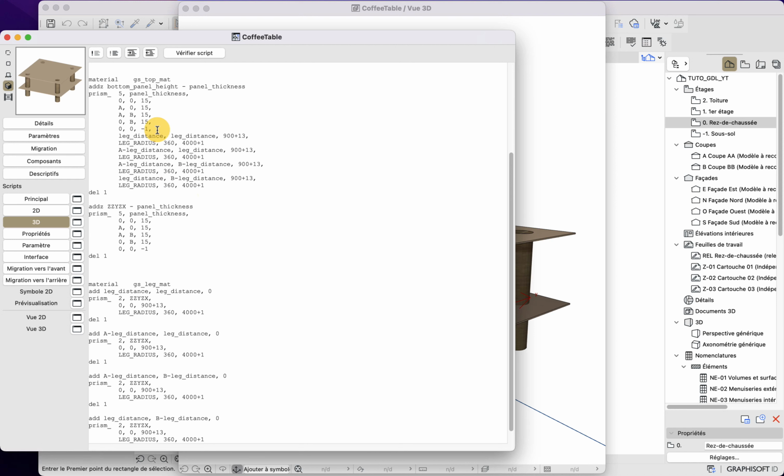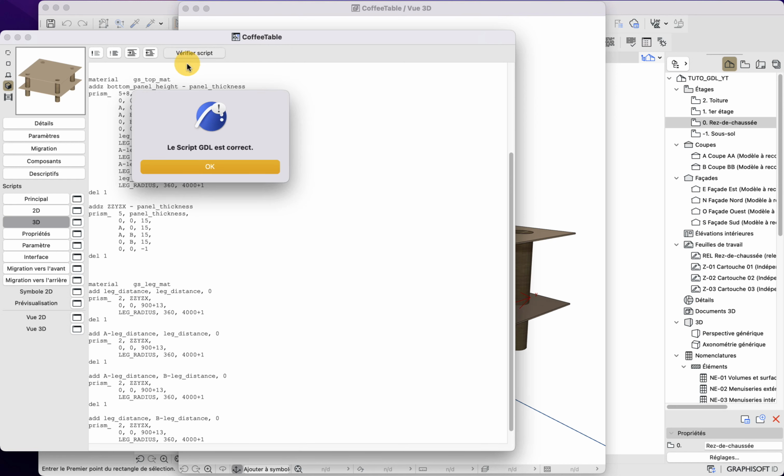I need to make sure that I have commas at the end of all of my coordinates except the last one. I also need to not forget to add a value to the number of nodes, because now we have 5 plus 4 by 2, so 8. And like this, we have our command that is complete.